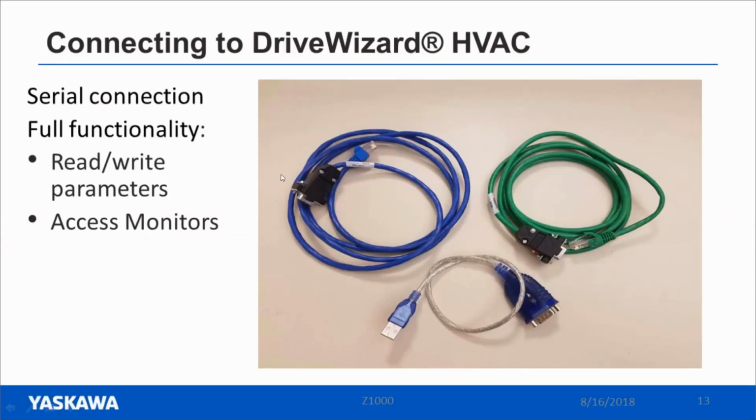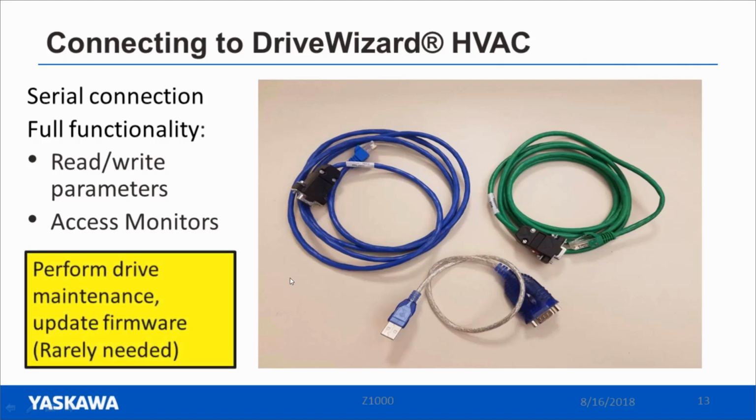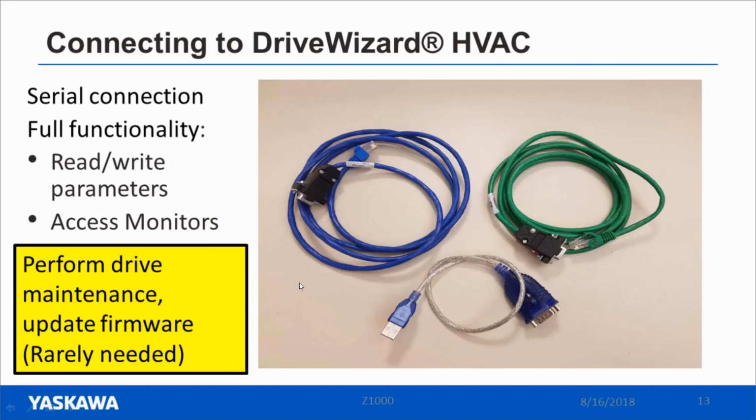And here's the serial cables, and this is the type that I would recommend, and I know our training group pushes this as well. You're going to have full functionality with these cables. So not only read and write parameters, and access monitors, you'll also be able to perform drive maintenance and mainly update firmware. And I need to mention that that is rarely needed. If you do happen to log on and see that you have an older firmware and there's a newer one available, that does not mean that you have to update your firmware. So keep that in mind.